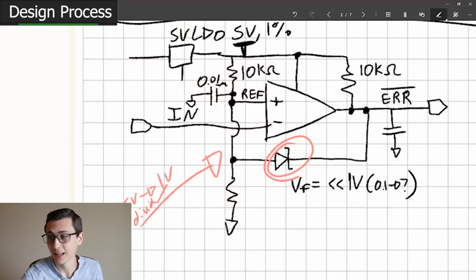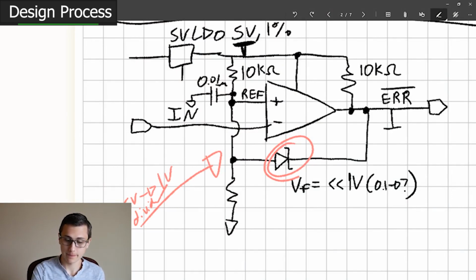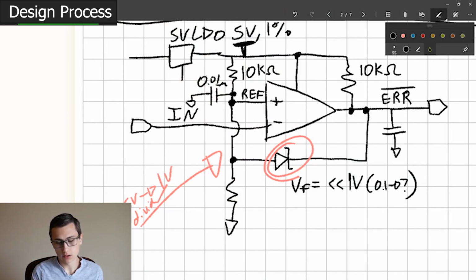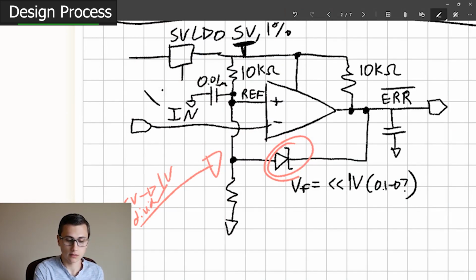If this is a critical overvoltage that shuts down your system, that's pretty important, because if the circuit doesn't work, your system won't power on ever, because every time it powers on, it'll trip this circuit. That could be a huge deal. Okay, enough rambling. As long as this input voltage is less than our reference, we'll be okay.